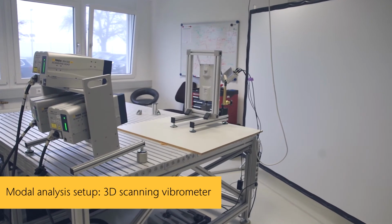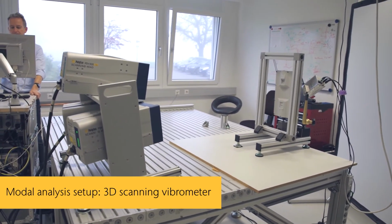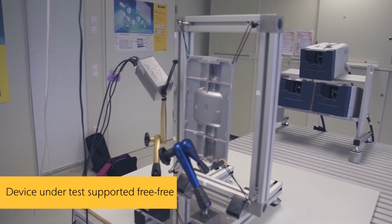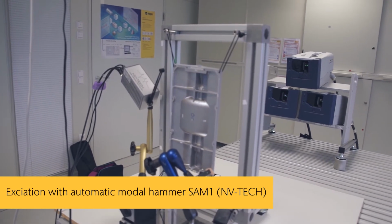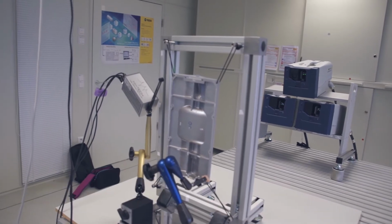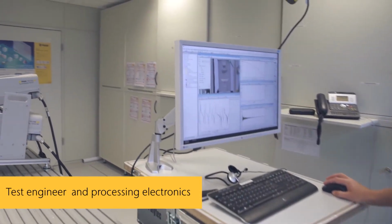So here we've got the test setup. We're using a 3D configuration with 3 scanning heads. The sample is supported in rubber strings for a free condition, and an automatic modal hammer, providing a consistent input force, crucial with nonlinear structures, is used to excite the structure. And of course we need an operator, software and some electronics.